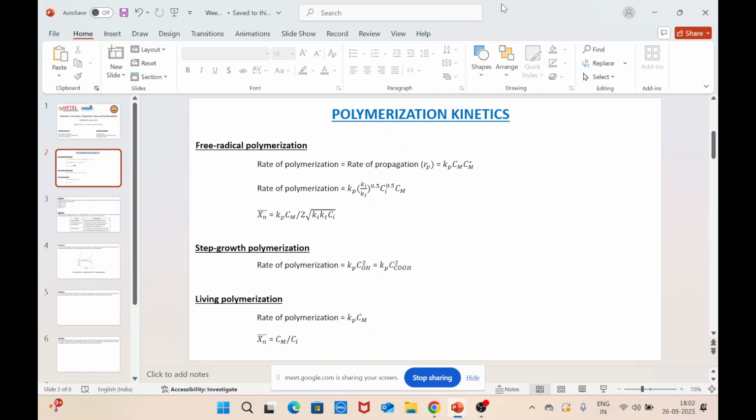So here what happens is, first, the molds for injection are usually in the form of two halves. These two halves of the mold are connected together, and the molten polymer is then injected into the mold, and it fills the cavity that forms after connecting the halves of the mold.